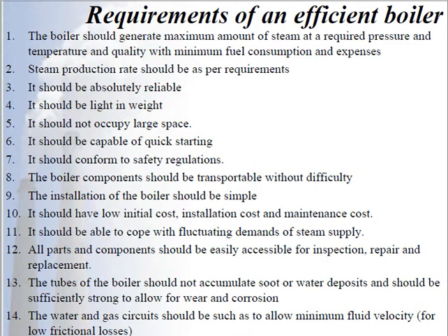It should be absolutely reliable. So obviously we will require a reliable boiler. Then it should be light in weight. Okay, so for transport condition, this is a main factor. It should not occupy large space. Okay, so that means less space will be used for those boilers. It should be capable of quick starting. Okay, for some of the boilers the starting process is so hectic, so that means it should be capable of quick starting. It should conform to safety regulations. So safety regulations and safety devices will be used for those boilers.